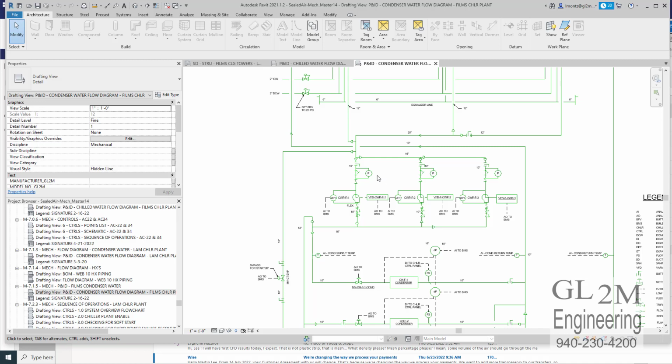We've even put differential pressure transducers there that will send an alarm so that they know when that strainer is clogged and they can get out and clean it. Again, it's a 24/7 operation, so it's all about reliability.